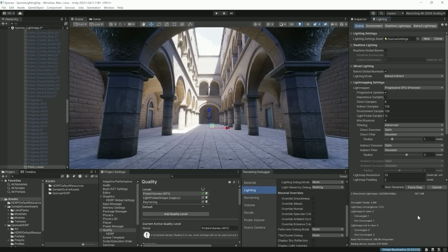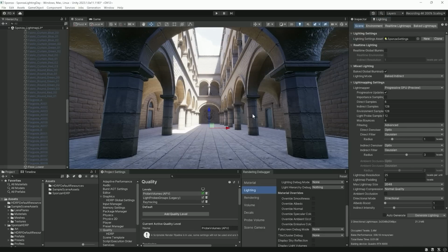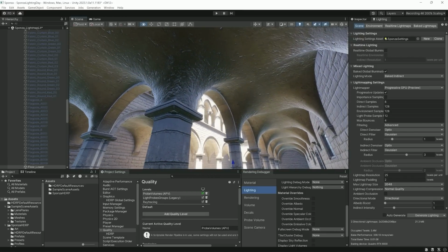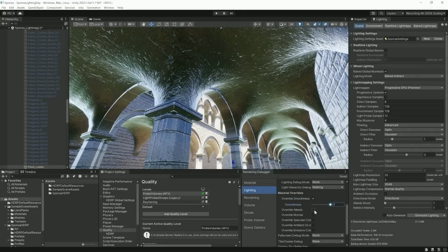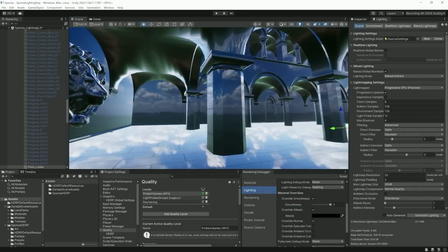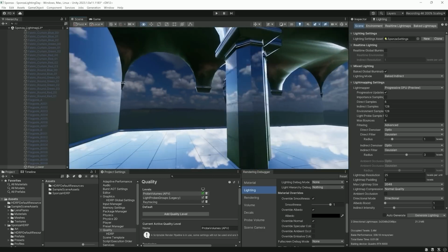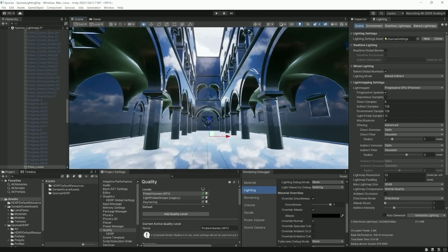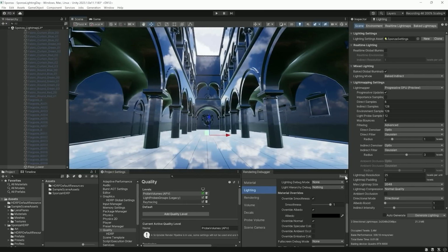The light maps are starting to converge. Near the end of the process, the light maps are getting denoised, compressed, and stored as EXR. As you can see, the results are not great yet. There is a blue and green tint on the materials. With the rendering debugger, you can see that the scene still reflects the sky entirely. But we can fix this specular leaking using an object called reflection probes.